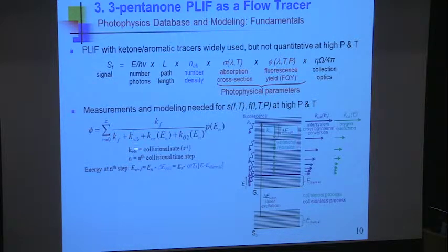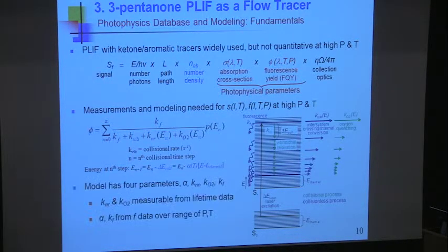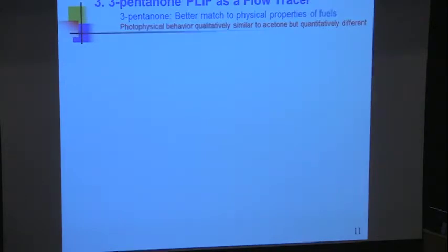and that was what we had to build this complicated model to describe this, only because we were working with variable temperature problems. If it hadn't been for that, we'd be okay. So if you go into a compressible flow field, you want to study mixing in a supersonic jet, you have variable pressure and temperature, and you have to build a model. And this model is now in place and is used around the world.